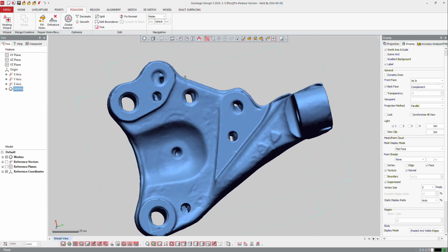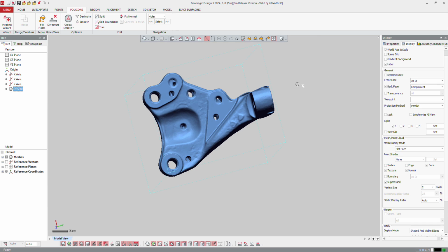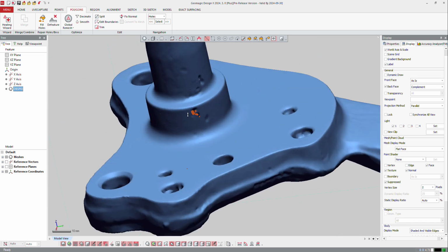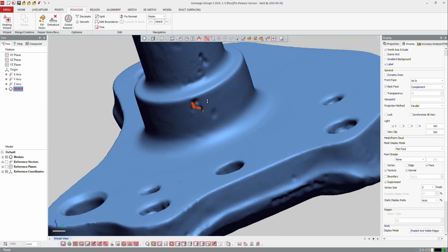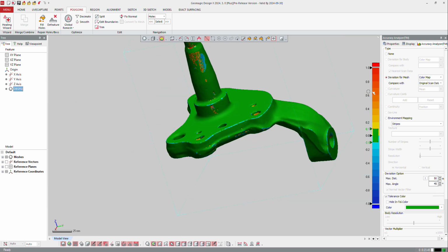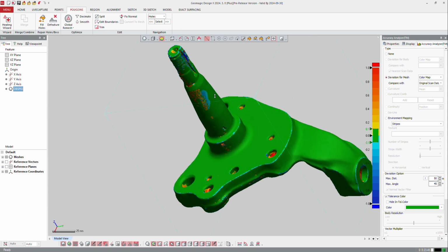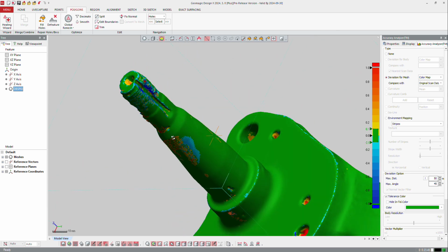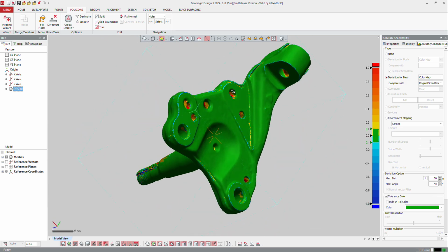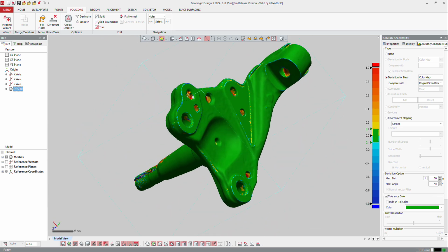And then here, I can check if this part is modified too much. So again, here I may have some defect, but I don't care. I just want to make sure that this part is okay. So I will make a deviation from mesh. And the software shows me the difference between that mesh and the original scan data. So it remembers what was the state of the scan at the beginning of the session. So it shows me where I modify and I remove some data. So of course, here I get some holes and I fill the holes. Software shows me some defect.